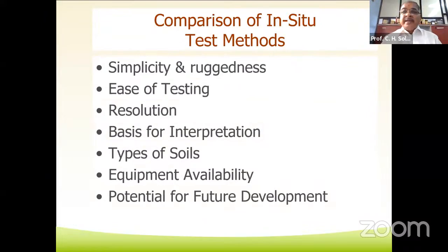Now, whatever tests we have discussed here, you can compare them on different points. Which one is simple? Simplicity and ruggedness, ease of testing, resolution, basis for interpretation, types of soils, equipment availability, and potential for future development. You can compare for your sites and take the decision for performance of the test.